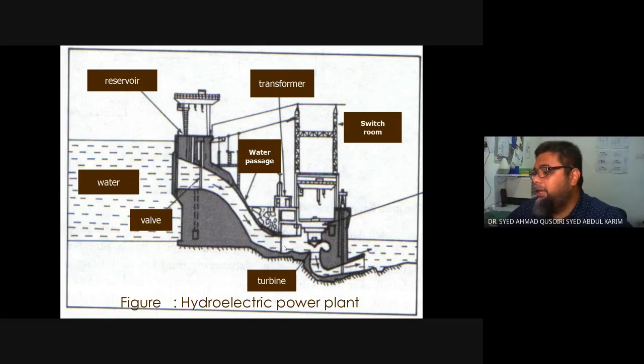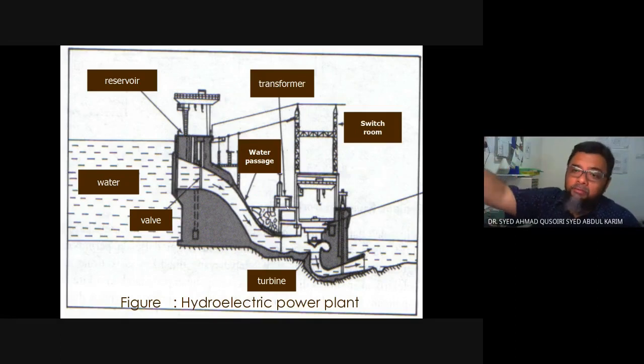Goes down and gets into where the turbine is. It will rotate the flaps of the turbine, which will turn the shaft, which will turn the alternator. And then the water will be ejected out. So once the alternator turns, it generates electricity, okay, at what, 20, 25 kilovolts. From there, immediately, but they do not want to put the step up transformer far from the source.